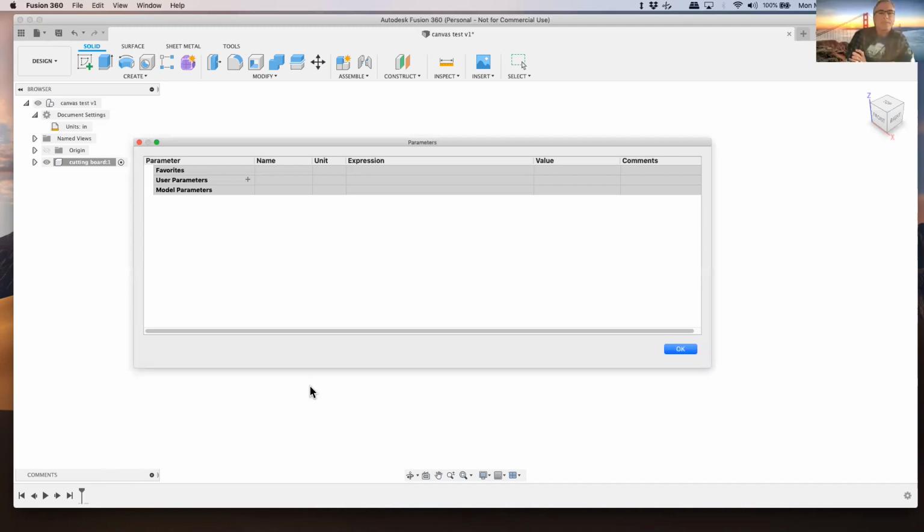Got it. And bring it up and having the whole sketch and then sorting through the sketch to find the dimension. It's just a lot easier. So real simple components, real simple parts, yeah, you can get away without using parameters, but in more complicated products and assemblies, you'll find parameters will save you time and just make your design easier to work with and modify, tweak, refine, hone, all that kind of good stuff.